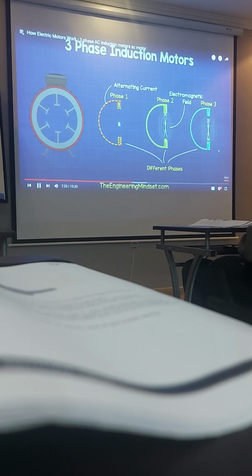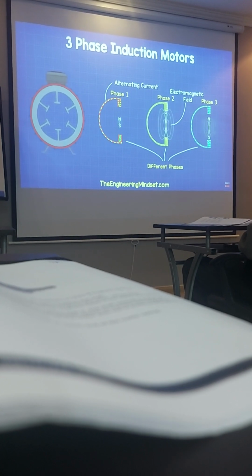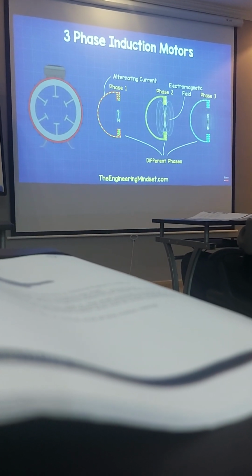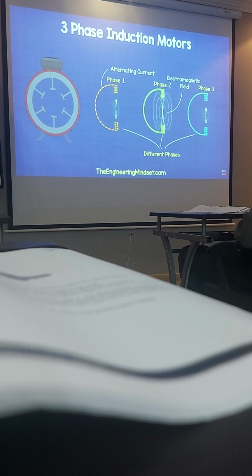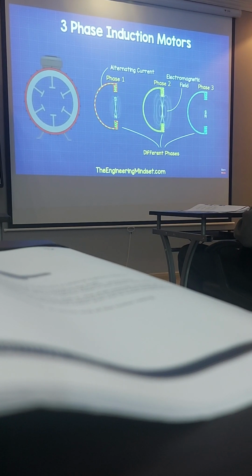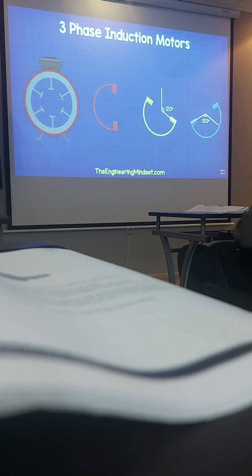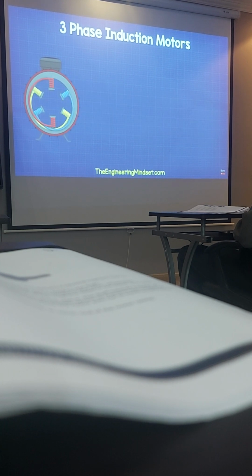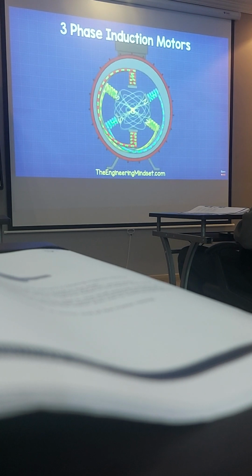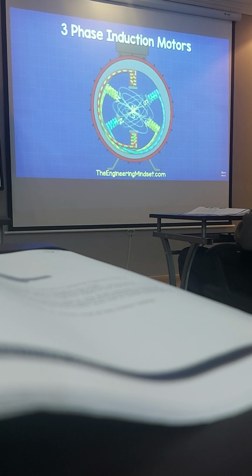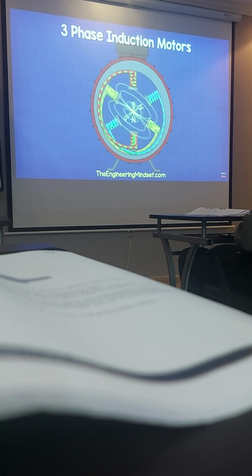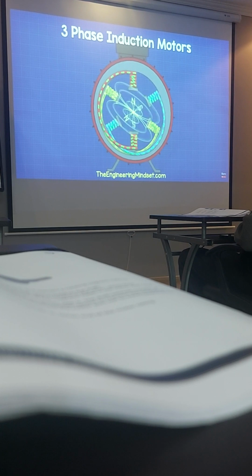This means the polarity and intensity of the magnetic field will also occur at a different time. To distribute this magnetic field, we need to rotate the coil sets 120 degrees from the previous phase. We then combine these into the stator. The magnetic field varies in strength and polarity between the coils, which combine to produce the effect of a rotating magnetic field.